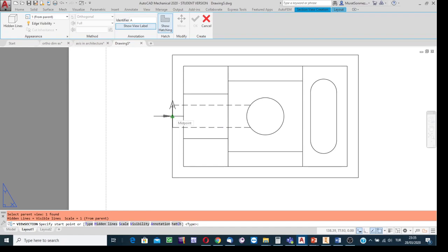Okay, bring the cursor to the vicinity of the midpoint of this boundary. It is at the symmetric cross section. To teach the software that we are going to cut the body at its symmetric cross section, do it. Move the cursor to the vicinity of such a point. It is the midpoint of the boundary. But don't click. Move the cursor away. Yes, a track line has appeared on the screen.